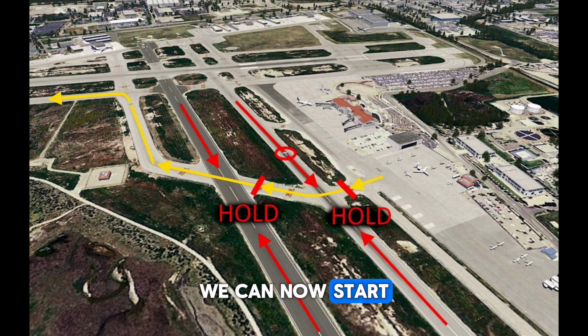Taxi. We can now start taxiing to the runway, but we have to do a run-up still. We'll make a stop in the run-up area next to the runway. Turn on the taxi light if required. Release the parking brake by clicking the black lever below the front instrument panel.